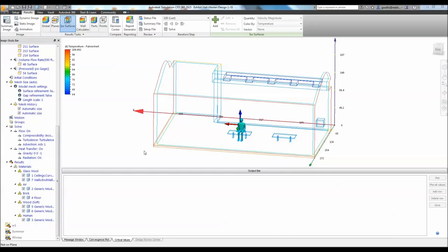Examples include offices, homes, libraries, stadiums, data centres, department stores and things like that. It is a way to characterise specific conditions in which a known fraction of the occupants will find the environment thermally acceptable. So in this step we will use the predicted mean vote, the PMV, to assess the impact of the design on the hall and the ventilation strategy that we have.